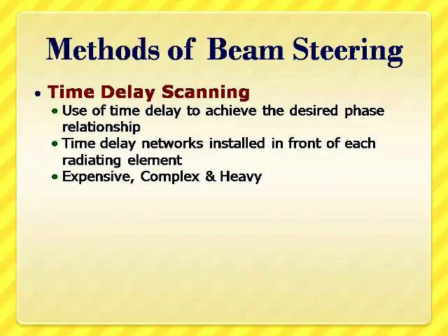First, time delay scanning. Use of time delay to achieve the desired phase shift to different elements. And time delay networks are installed in front of each radiating element. But what is the price we are going to pay for this? Definitely it's going to increase the complexity of the network, and those elements are heavy. Moreover, it's going to be finally an expensive proposition.